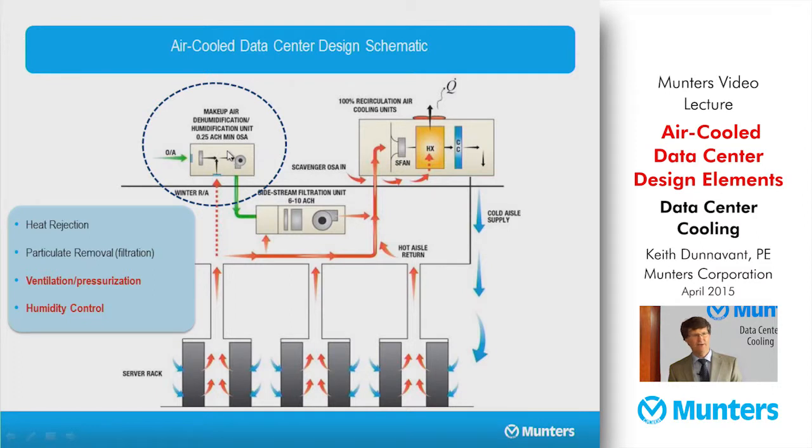Secondly, you want to have dehumidification installed in this device so that during all of those ambient hours where the dew point is well above, usually 55 to 59 is the upper end of recommended.